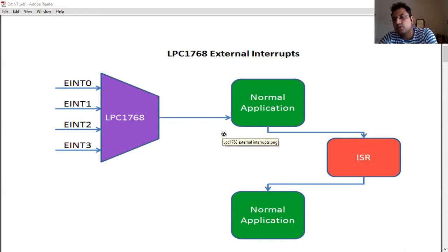To handle that, somewhere you will write in the interrupt what exactly we want. Once the interrupt handler takes care of it, after interruption takes place, what exactly do you want to do? For that purpose, your interrupt service routine will take charge. After completion of your code corresponding to the interrupt, your system will resume back with normal operation. That is the simple, layman understanding of the interrupt.